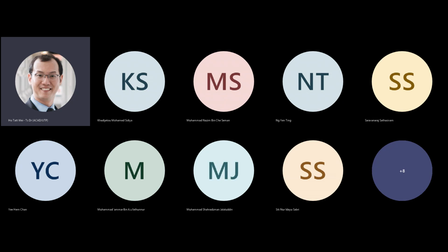And then you get a special kind of tool that would have a small patch here to be implanted with a different type of material, let's say an N-doped material, for instance. Then you could have another region here, which is an N-doped material, and then you would use a mask. You would dope silicon dioxide here. That's a dielectric insulator, and then you deposit a metal connective layer here. So that forms one transistor, and you then have another region here, P layer. You dope a bigger region here, N, and you dope P-type material here, P-type material here.